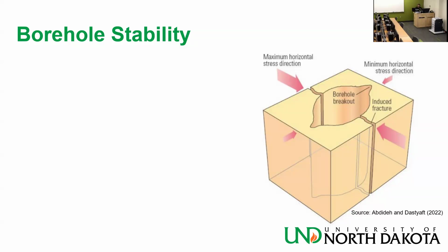When I'm drilling a wellbore, it's impossible to have the exact mud weight every time. I drill it, I get a little bit of failure. We learned in drilling that when you drill a wellbore, you need to be higher than the pore pressure and lower than the fracture pressure. You need to be in between. The examples that we gave are pretty wide windows. Now, this is not always the case. You're always having a little bit of an error.